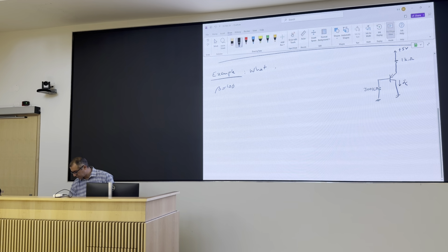For a large VCE, you get this much larger current. Not that much, a few percentages. You go from 1 volt to 10 volts, especially for big off-the-shelf transistors, and the difference is 2%, 3%. You probably won't notice if you don't look there, right?